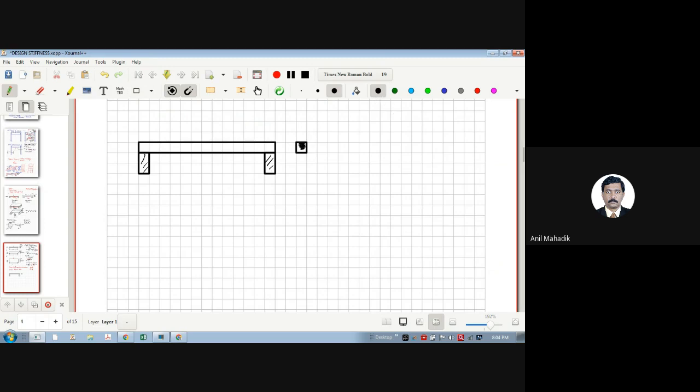Solid rod, square rod, let's say. So this is having area A, say, for example, and this will bend for this span and due to some loading, whatever. Then if you want to increase the moment of inertia, what we have discussed is that you can decrease the B and increase the D. So in the second case, but in that case, we cannot do rectangular shape because in steel structures, you might have seen the sections are not rectangular mostly. So what is the choice?